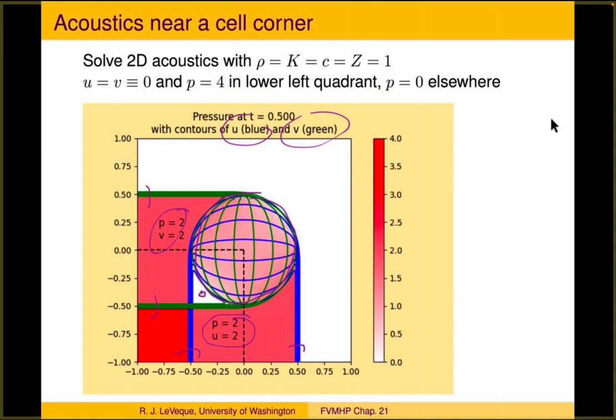So in our finite volume method, using these transverse waves, we're essentially approximating what's going on in this circular region by using this wave that's propagating to the right, but then also propagating it up in this direction. And similarly, this wave that's propagating upwards, we would also be propagating part of it after we do the eigendecomposition in the transverse direction in this direction.